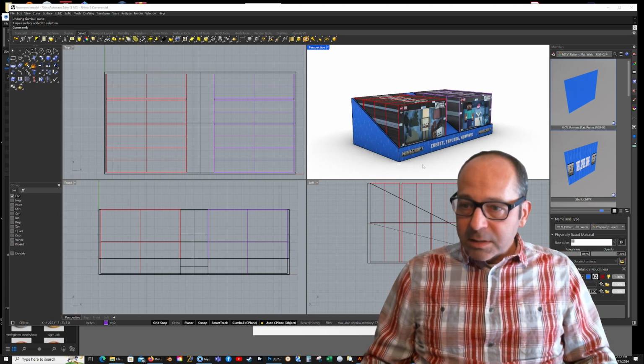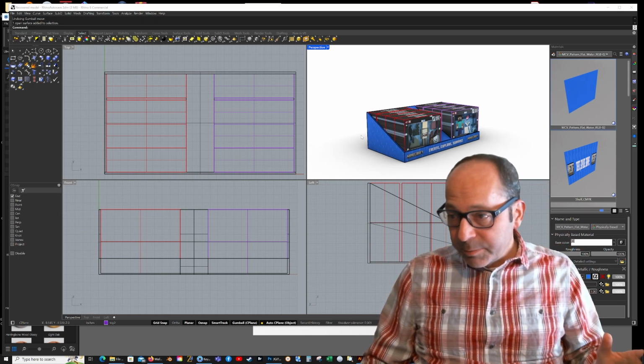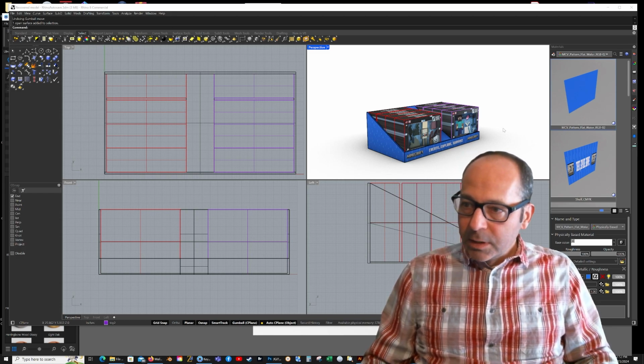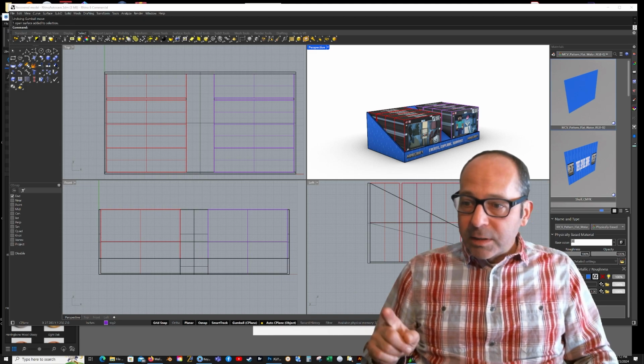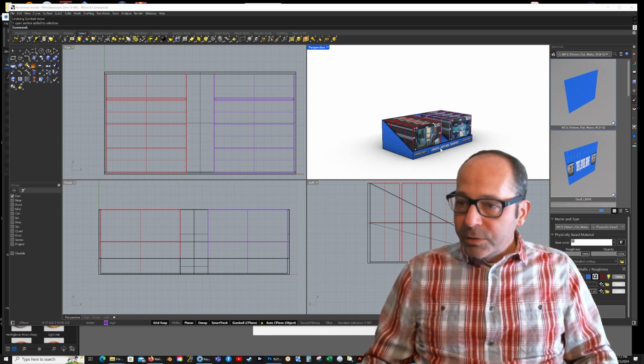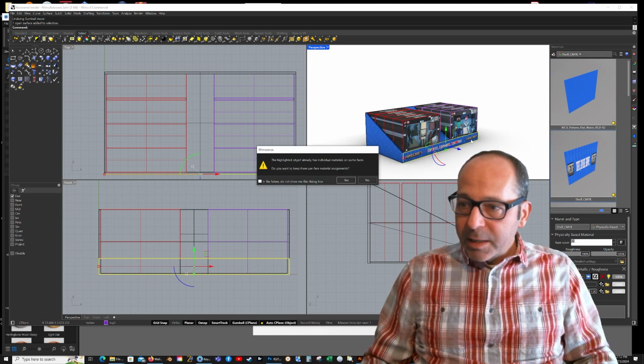So now that it's exploded, originally you want to remap it, or just initially map it using all mapping channel 1. And now that it's separate objects, that's not an issue. But now that we have this and we don't want to remap everything, all you really have to do is reapply the map and you get this dialog box.